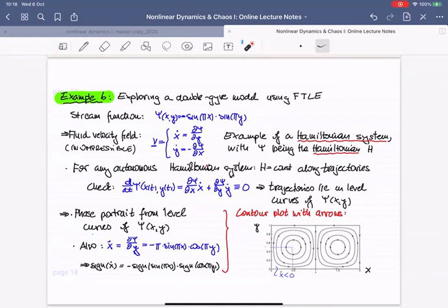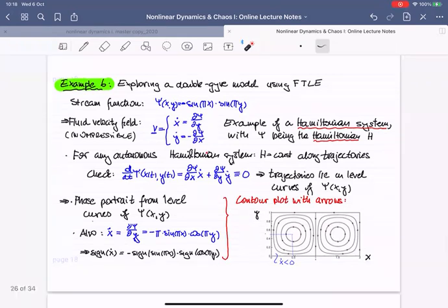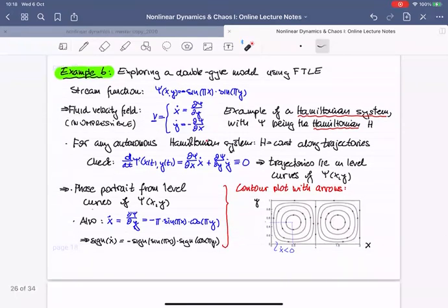Even in a general 2D flow, the flow is unsteady and the stream function is not given to you. Even if it was given to you, it is not a conserved quantity, so it's not helping you. Its instantaneous level curves, the streamlines, although they are thought to be very important in fluid mechanics visualization, certainly don't tell you where the material, the actual fluid particle, goes. Although in fluid mechanics, people still have a hard time believing that. They teach it in all the classes. That's one of the introductory facts. They teach you that streamlines are different from particle paths in fluid mechanics.